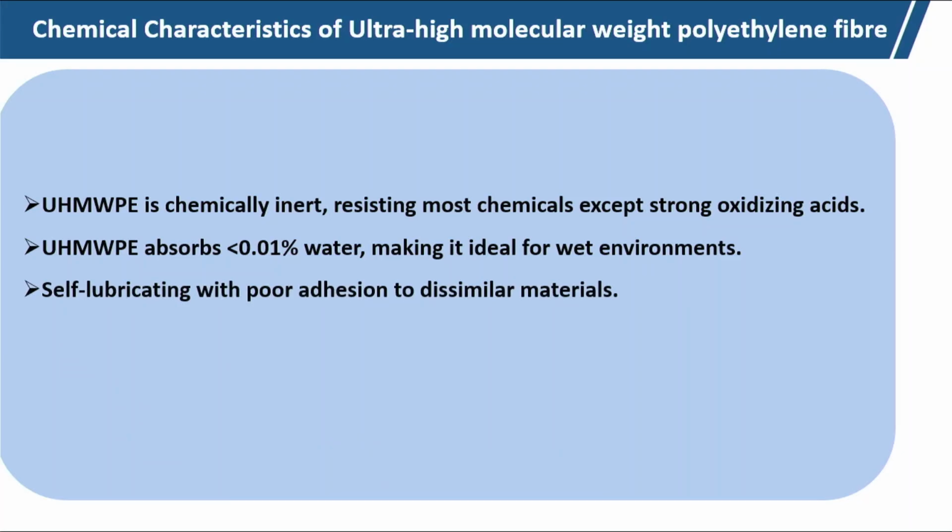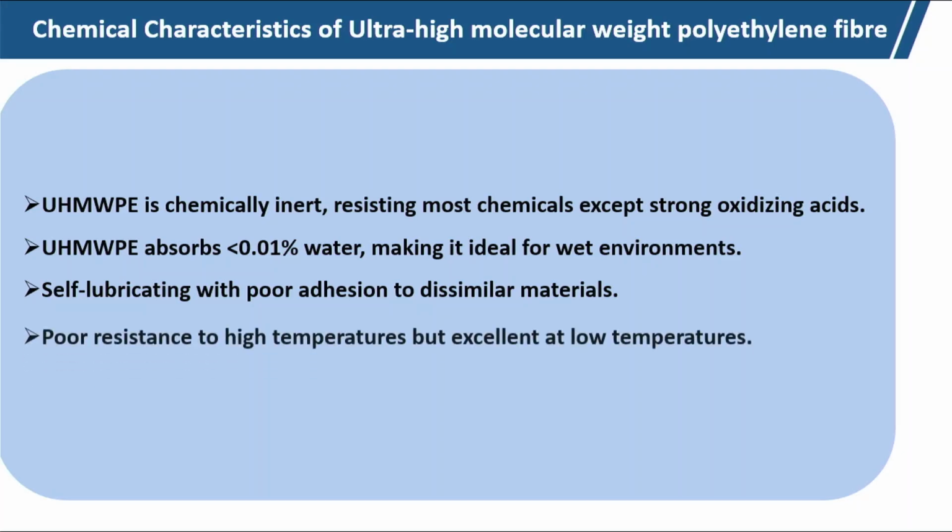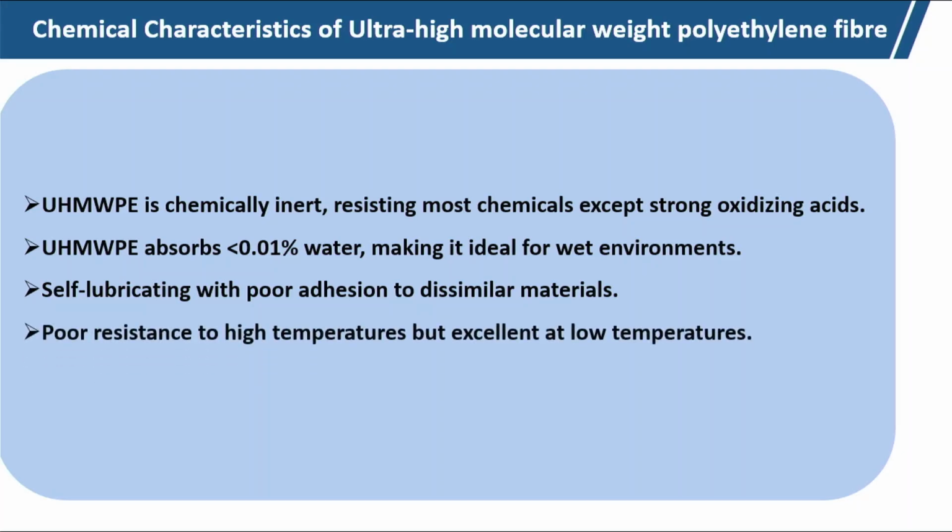Self lubricating with poor adhesion to dissimilar material. So, it is a self lubricating material, with poor resistance to high temperature, but excellent at low temperature. For high temperature applications we do not use this ultra high molecular weight polyethylene, but at low temperature it retains its strength and all other characteristics very well.